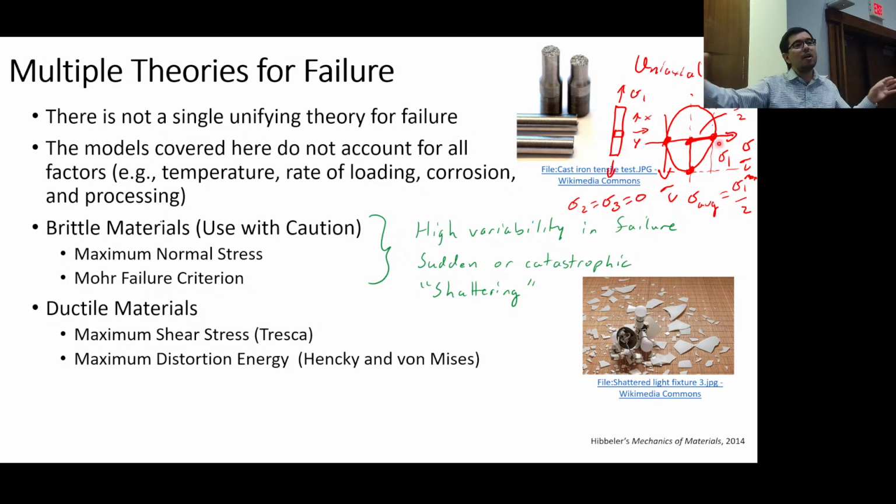So now we are thinking about a radius expanding on the Mohr circle, and we expand it all the way out to the yield strength. And then we see that the absolute maximum shear stress is going to be that yield strength divided by 2.